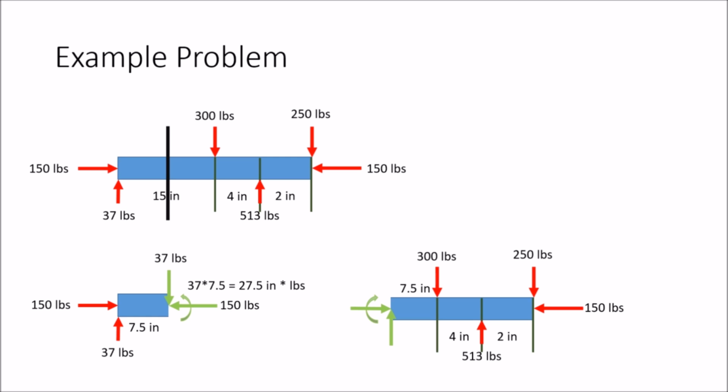Looking at the other side, we would do the exact same process, summing forces in the x and y directions and taking a moment at the cut. But everything is more complicated since there are more forces acting on the beam. But in the end, we will get the same values.